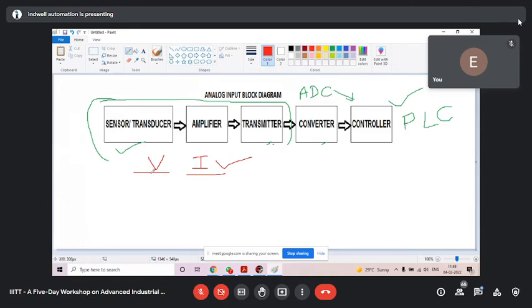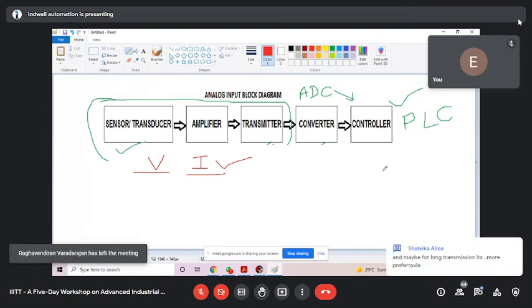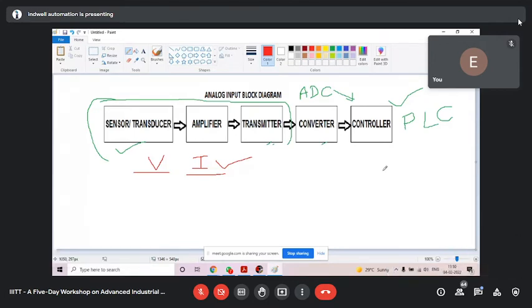See, when we take a voltage signal, your tank can be away from the PLC. Obviously, it would be far away from the PLC control panel. So one wire will come from the transmitter to your control panel, PLC panel. So you have a long distance wire. Or let it be short distance also. When we have wire, we have resistance, we have voltage drop. It is sure.